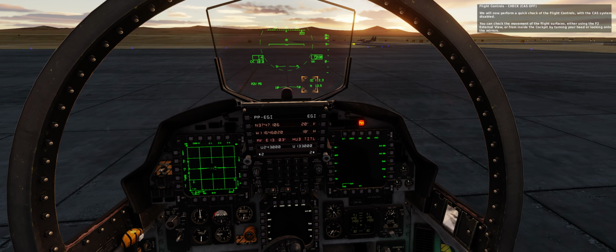Anti-skid, check norm. For this check, the anti-skid should be enabled. Press spacebar to initiate the check. Flight stick full aft and left. Observe stabilator trailing edge up, left further up than right. Rudder left. Press the stick's trigger to continue the check. Use the spacebar as well.